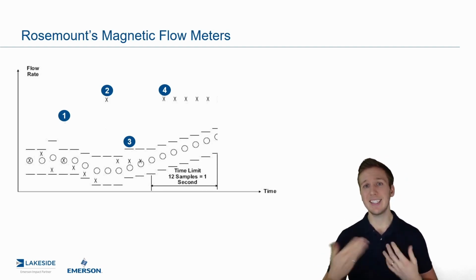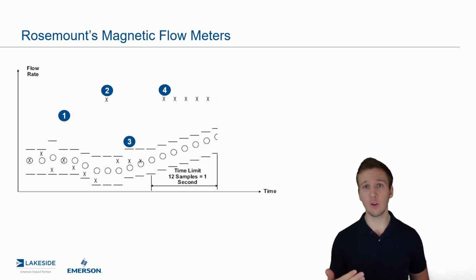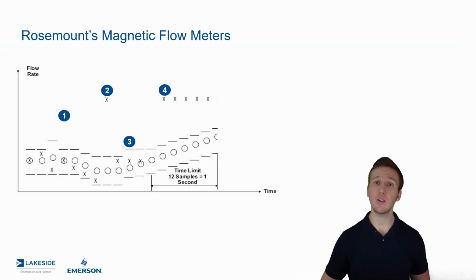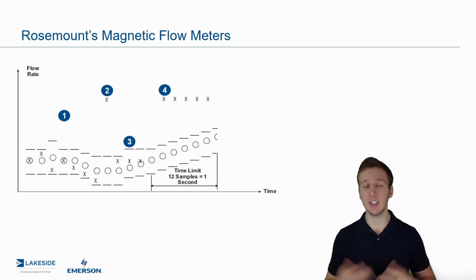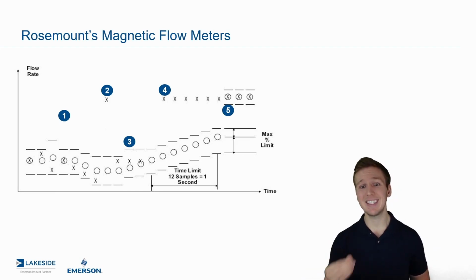And then what you're seeing is consistent measured values at that data point, validating that the true flow rate is actually at this point, even though it's way beyond that threshold. And so the algorithm will step its way up to this in a gradual fashion until in point 5, we now have a tight threshold around this point because we're getting very consistent measured values at this elevated point.